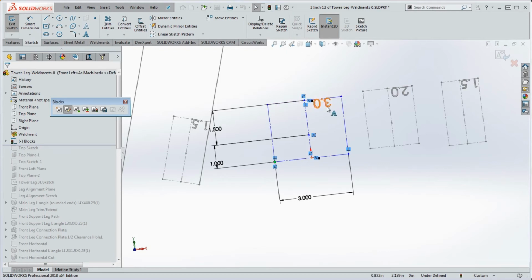And we have sketch text in here, which defines the value of the structural member we're going to put in place. So again, we're going to be putting all this stuff in regard to a sketch, all these sketch elements together. We're going to get that fully defined in our model before we even put in a structural member that goes in place. So you want to make sure that when you're putting your structural member in here that it's going to be of the proper size.